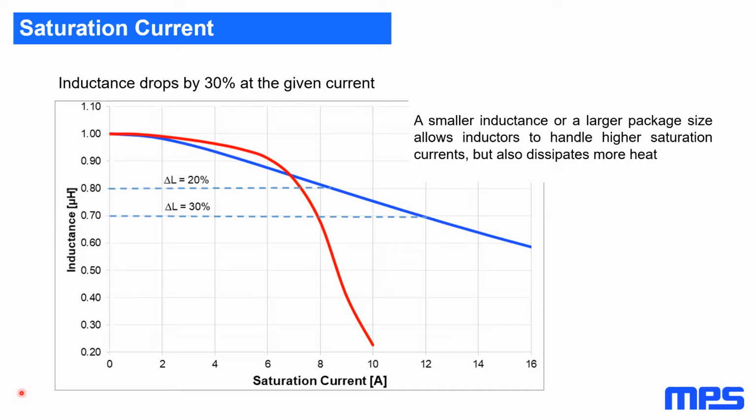Also the saturation level. When we have a molded type, we have an air coil pressed with powder material, forming an inductor. This is the molded inductor. So we have the best use of the component without empty spaces, as you see here. There is no empty space in between, so we will have much more core material, and this is also increasing the saturation level.